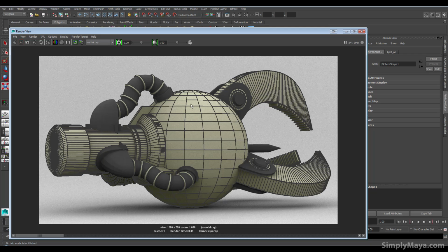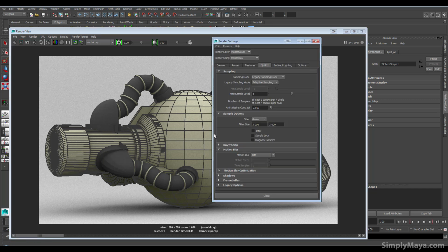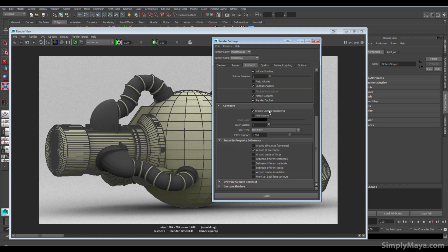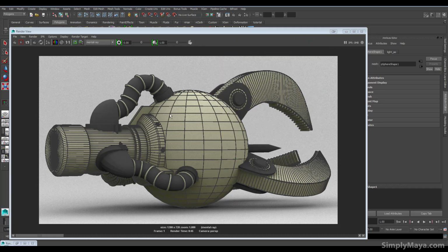As I said, we've got this contour rendering happening now, but it's massively thick. But it does work as an illustration that this is actually only working around the one surface shader. It's not working in the background, and it's not working on here, because apart from turning on contours, let's have a look, in here, you also need to arm them for each individual material.